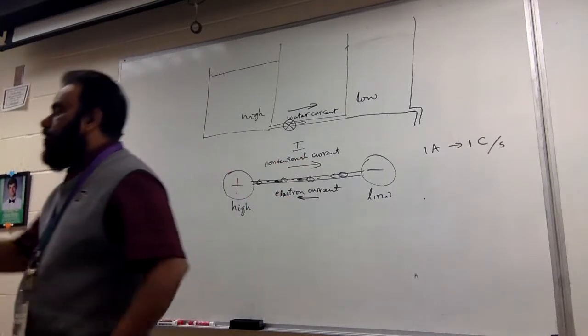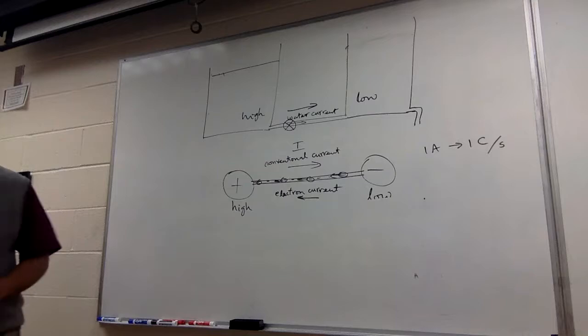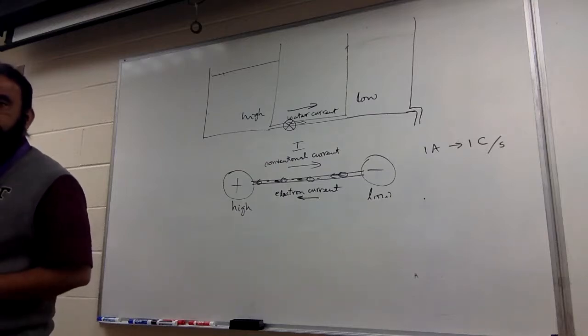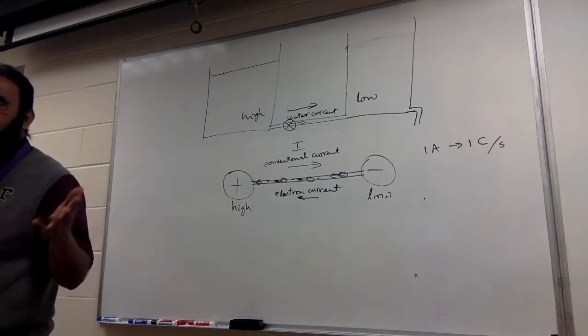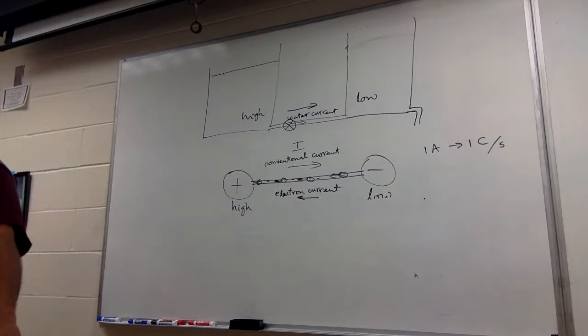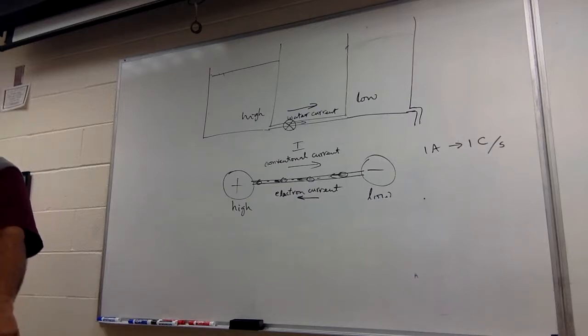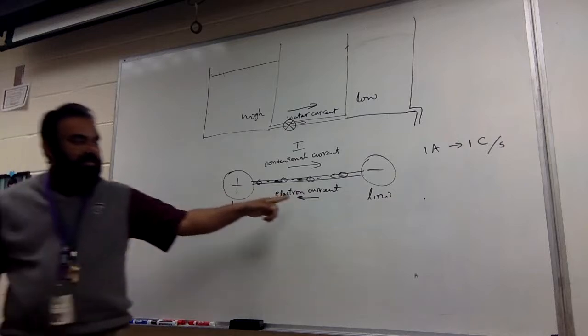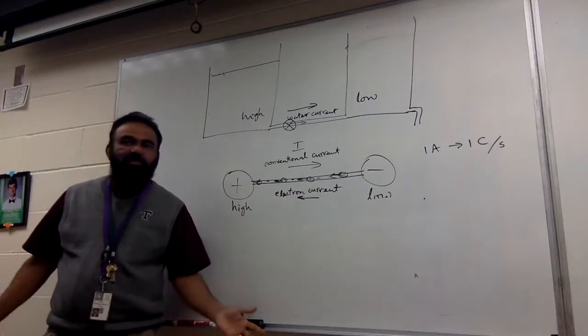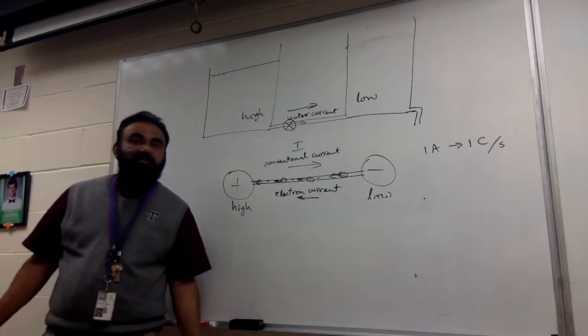So if I have 1,000 volts over here and 1,000 volts over here, exactly 1,000 each, I can touch it and I should be perfectly okay. I'll be at 1,000 volts potential, but there is no potential difference. You know what I'm saying? If there's a potential difference, that's when you have a possibility of a current. If there's no potential difference, no chance of current.